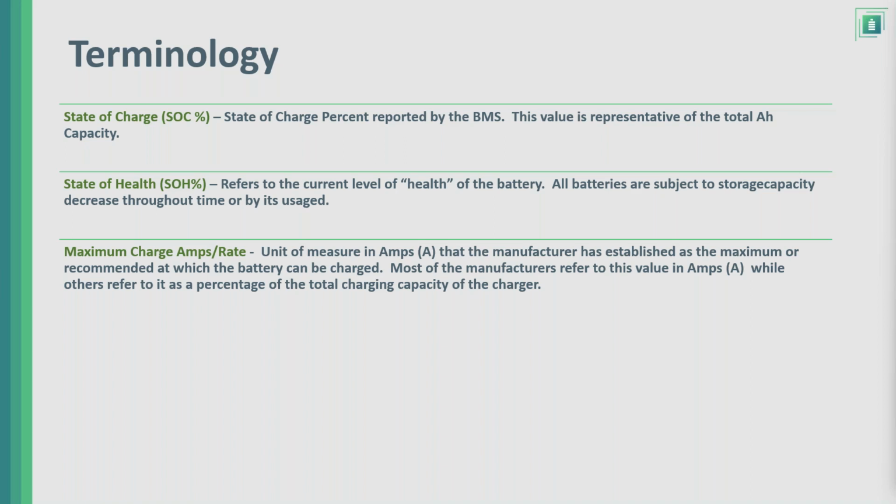Using the wrong value in amps used to be one of the major problems before, when we had lead acid battery banks, or when we were using open loop configuration, because as I mentioned, the parameter had to be entered manually. Any mistake or misinterpretation of the information provided by the manufacturer will eventually damage the battery, because it's being charged in the wrong way.